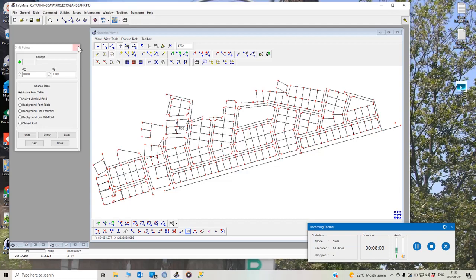Now, if you choose 2 or more points to do your transformation, you may find that your source points and destination points do not match exactly, and you may introduce residuals, which means that when you do the transformation, your distances, which were 20 and 40 meters, may now be 20.12 and 40.68, for example, which will cause you all kinds of problems, because now your directions and distances will not be rounded numbers, and it may distort your layout, and maybe that is not what you intended in the first place.